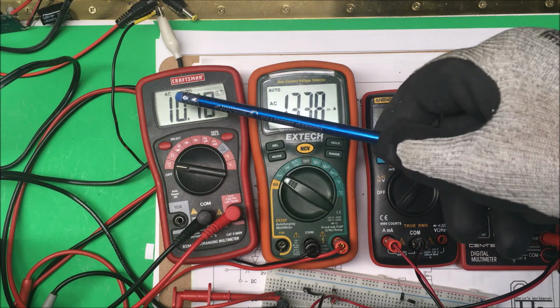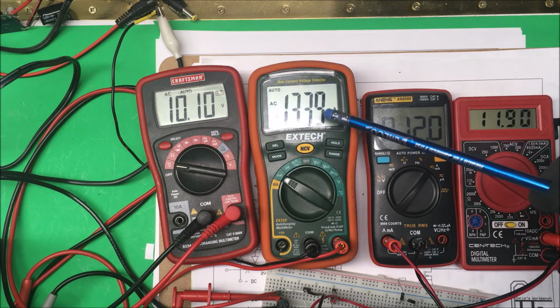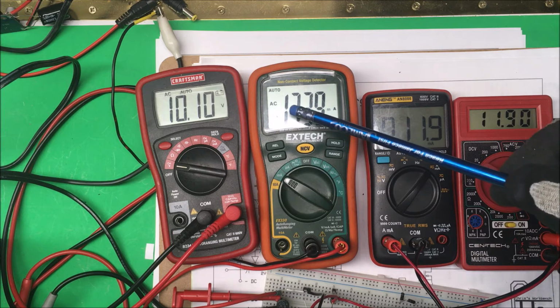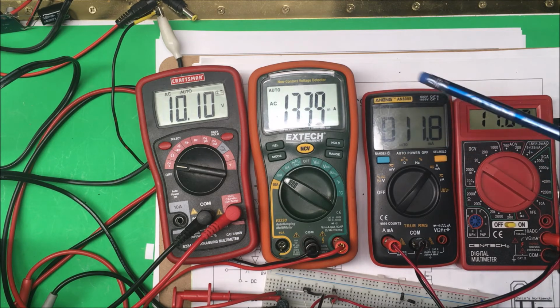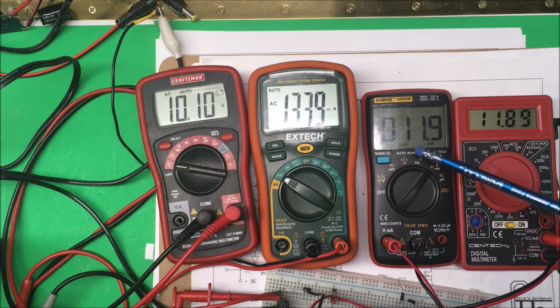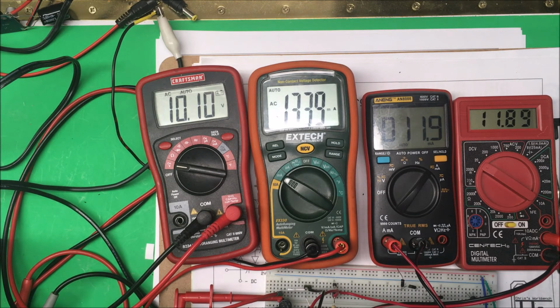All right, so we have 10 volts, and this is our current here, in milliamps. We have 13 milliamps going into the AC, but coming out here we have 11.9 milliamps. We're going into a 1K resistor, and then our voltage is going to be 11.9 volts. We had calculated 12 volts, but I'm sure I have some other losses in here that we're not looking at, but that's pretty good. We started off with 10 volts AC RMS, and we ended up with close to 12 volts out here.